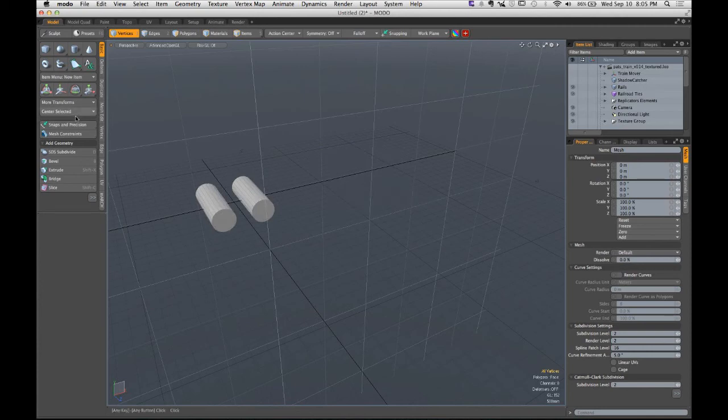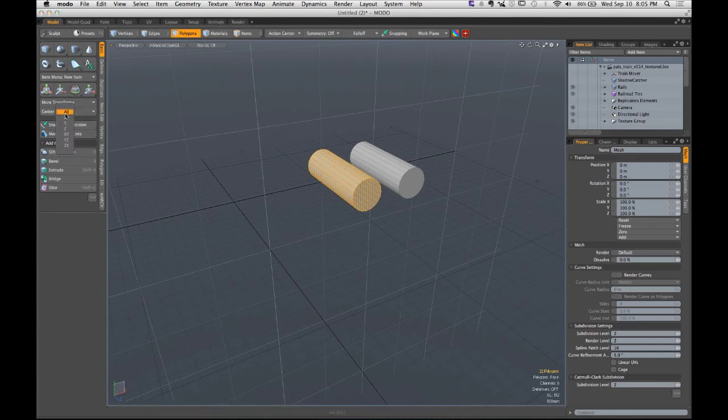Oh, so they're still not the same region. How could I get them in the exact same spot? You'd have to center one and then center the other. There it is. Individually manipulate them. You got it. So I could go in, center selected all, then go back to this one, grab it, center selected all. Now you don't want to do this. That's bad because now we have geometry on top of each other. Overlapping geometry is bad.